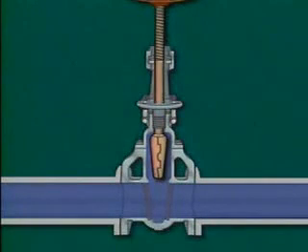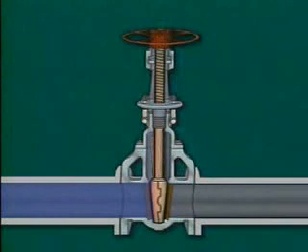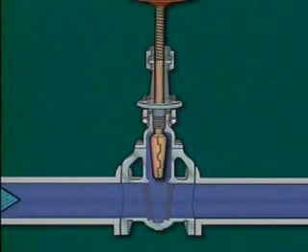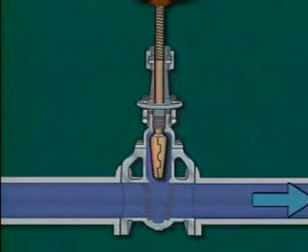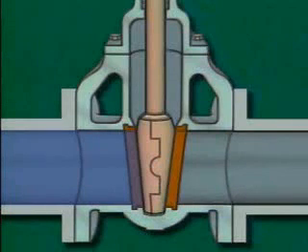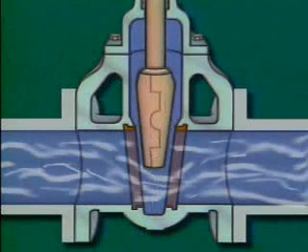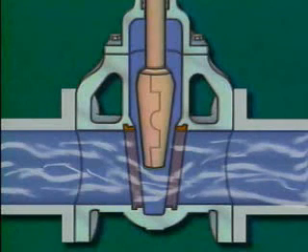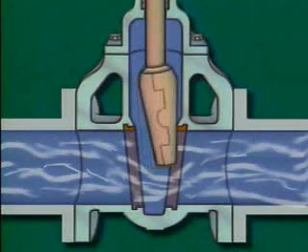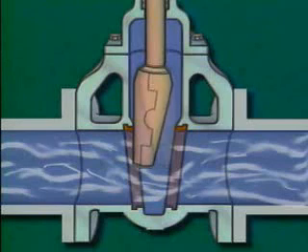Gate valves work best when they operate in either the fully open or the fully closed position. When a gate valve's disc is completely raised, fluid flows straight through the valve with little obstruction. However, if the disc is partially raised, a space opens on either side of the disc and fluid passes under the disc. This type of flow creates turbulence and causes the disc to swing from side to side, banging or chattering against the seating area. The chattering quickly leads to wear on the seat and the disc. Eventually, the damaged valve won't be able to shut off flow even when it's fully closed.